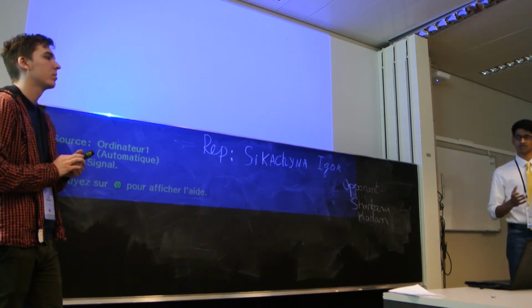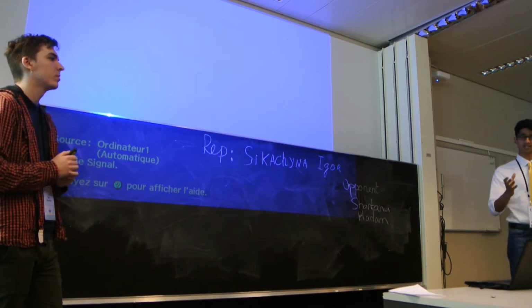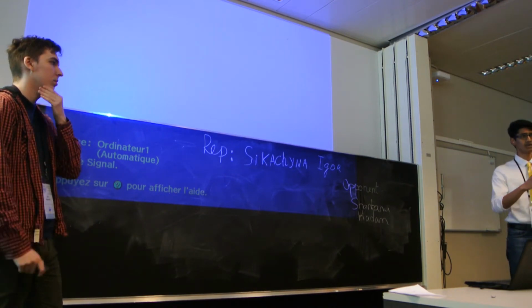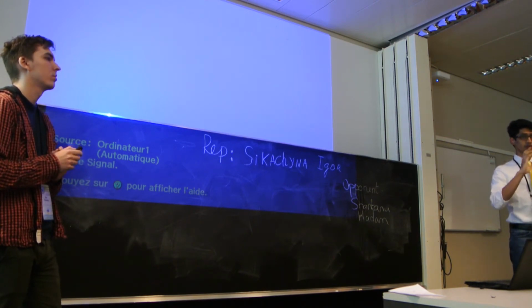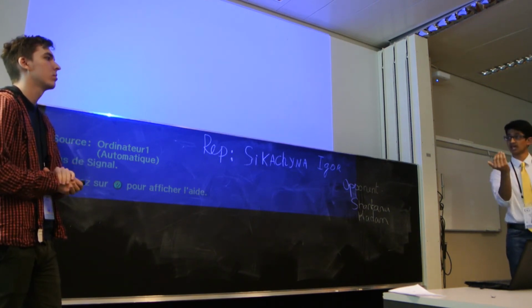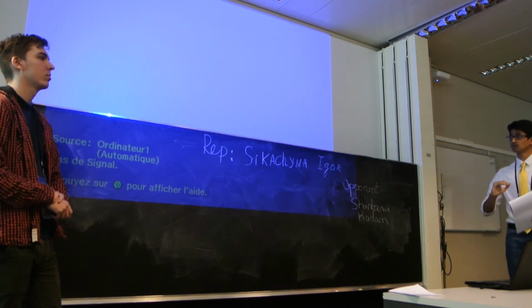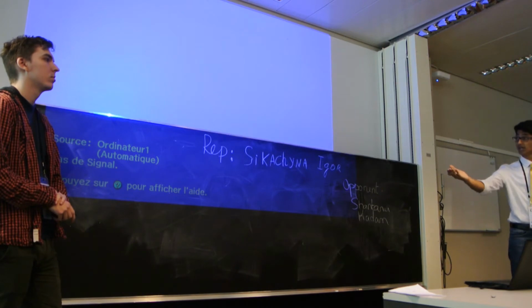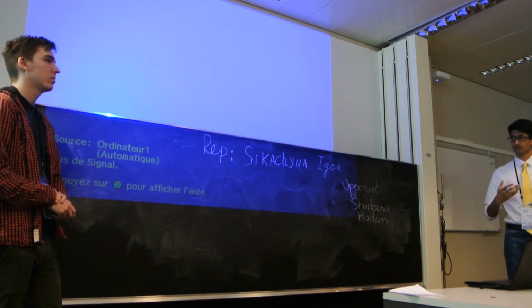It seems to me there are some types that you did not consider that would perhaps be meaningful to consider, as well as simply the construction of the rail itself, in the sense that there are different aspects to the rail. If you look at a cross-section, there's the rail head, the underhead of the railhead, the side of the rail, and then there's the rail bed. All of those will influence the dampening, the attenuation, as you mentioned, in different manners, and lead to different warping. So I would greatly appreciate understanding how you eliminated certain aspects and decided which ones are the most important.